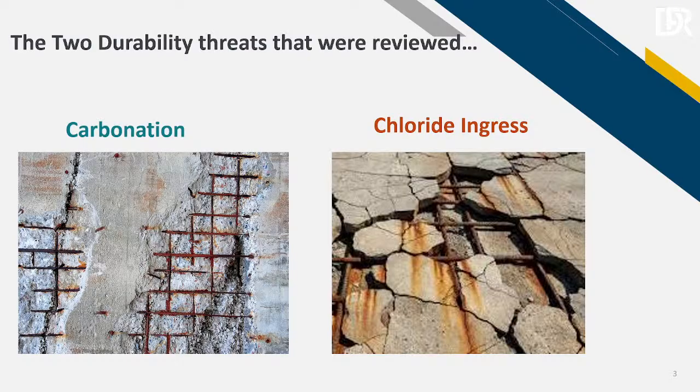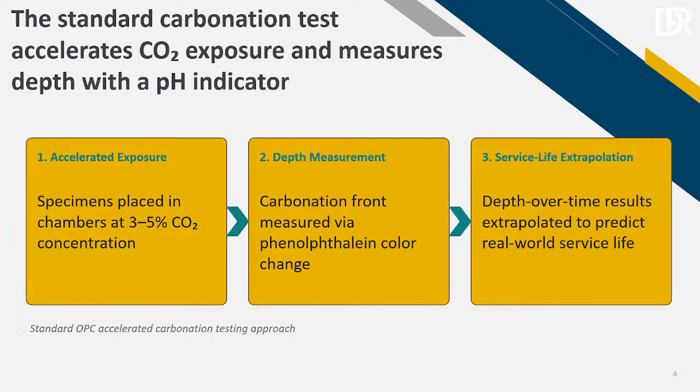So when you de-ice the pavements, or it's close to sea salt water, diffusion happens, and that chloride moves from high saturation to the inside of your concrete, which has no chloride, and then a similar thing will happen: the rebars will lose their protective barrier and they will start to crack. So that's the definition of what we are trying to look into.